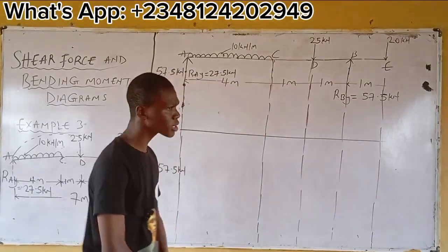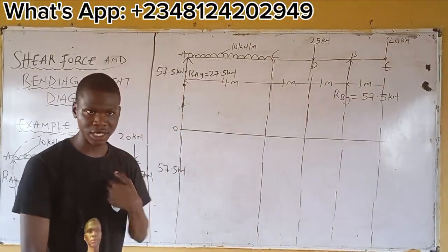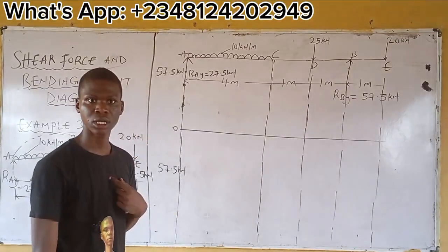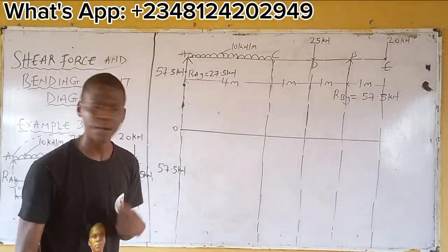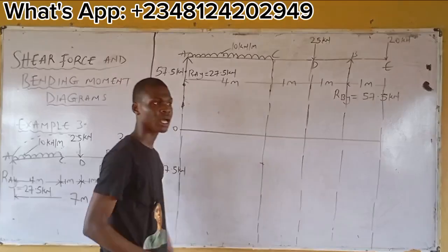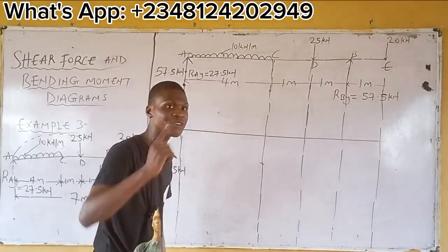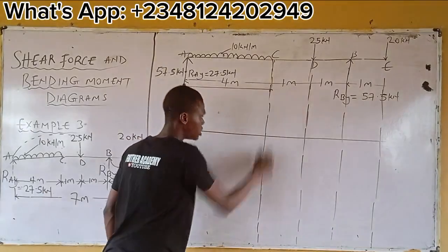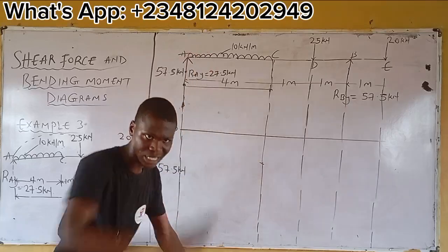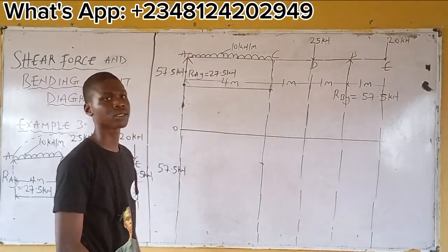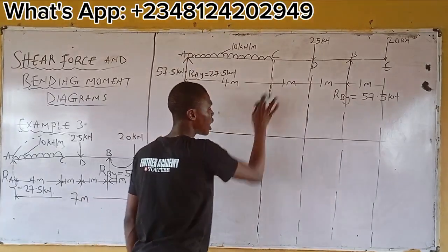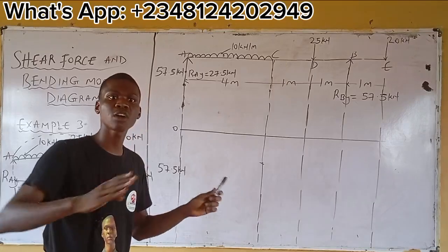You can say that I know what I'm doing. Looking at this, I know if you are telling me rubbish, because I know the expected diagram for shear force. If you tell me you have two values at C, it means I'm having a value here and a value here. At the end, if you want to draw the shear force diagram, it becomes this to this, which is wrong for a U.D.L. It is totally wrong. A U.D.L must be slanted. So at C, how many values do I have? Just one, which is minus 12.5.